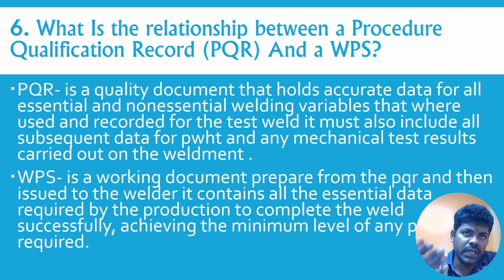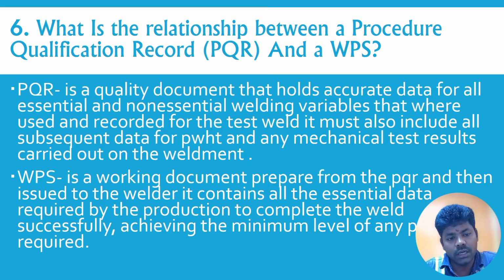So first we do the job with the PQR, then the PQR is accepted and approved, then we prepare the WPS from the PQR. We use the WPS at the site. The WPS is prepared and given to the welder foreman and welders.